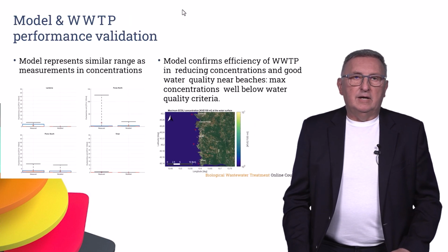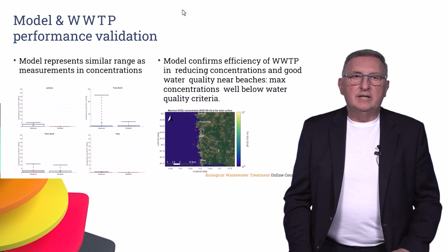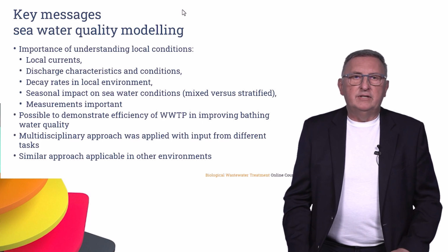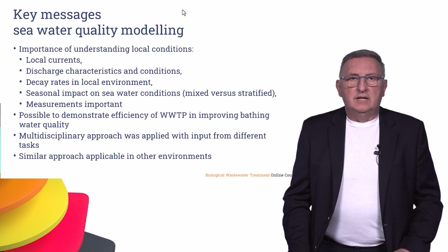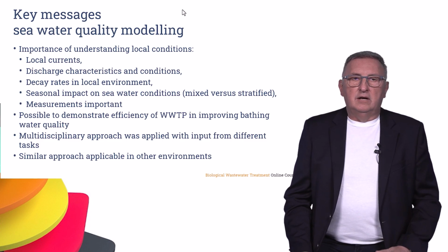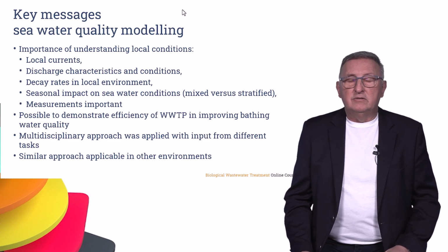Then we applied validation of the wastewater treatment and seawater models, and we looked into all kinds of parameters and sensitivity analysis. We came up with the main message that seawater quality modeling is really important, because it brings understanding of the local conditions: the local currents, discharge characteristics and conditions, and decay rates in the local environment, which are really low.